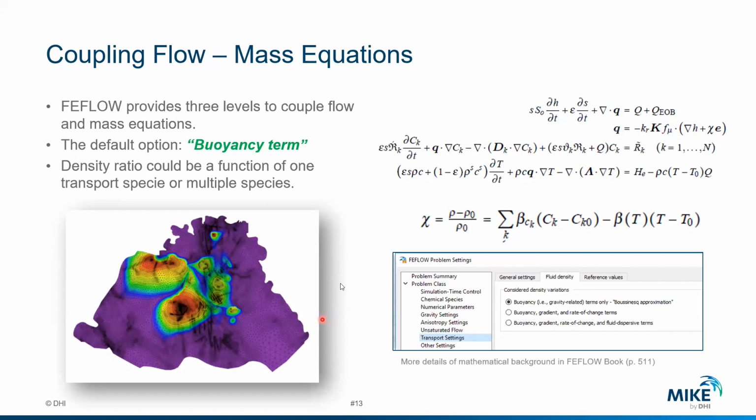So when we say density-driven flow, we start introducing the new terminology called coupling of the flow and mass transport equations. Normally, in every flow and mass transport problem, you solve the flow equation first, and then in the next step, the mass transport equation within the same time step. Then you go forward to the next step, and again comes the flow equation and the mass transport equation.